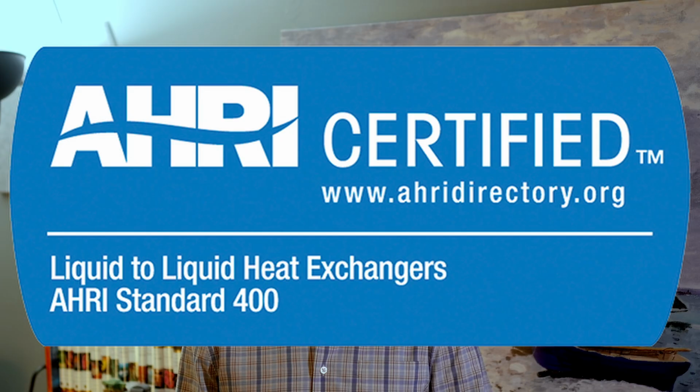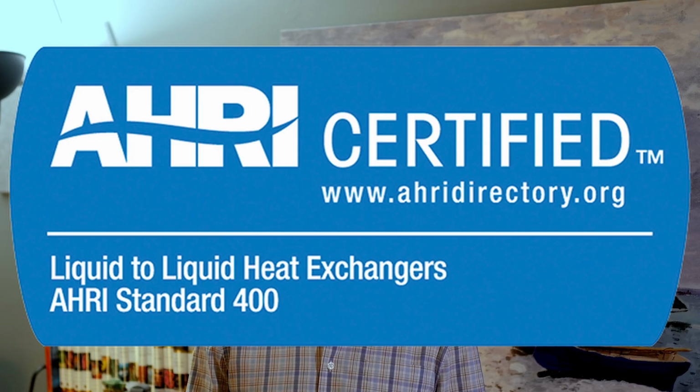If you absolutely need to specify a safety factor, the best practice would simply be a flat surface area adder, like 5% or 10%. However, since modern HVAC heat exchangers are AHRI certified, your best bet is to just right-size the heat exchanger and call it a day.